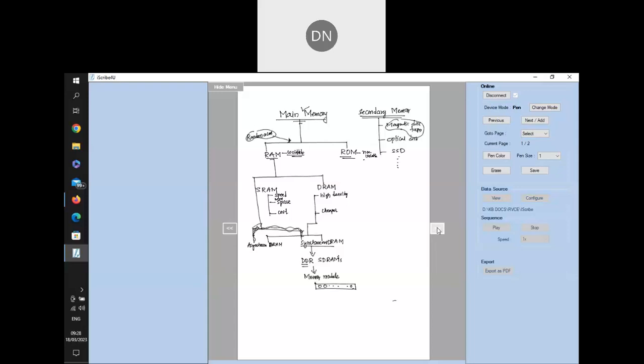Whatever the two types of RAMs specified, one is called asynchronous and the other synchronous. They come under the DRAM. It is not under the SRAM. SRAMs are standard. Only one type of SRAM is there. SRAMs are generally used to build cache memories. DRAMs are used to build the main memory of PCs, main memory of personal computers and laptops. So just make a note here.